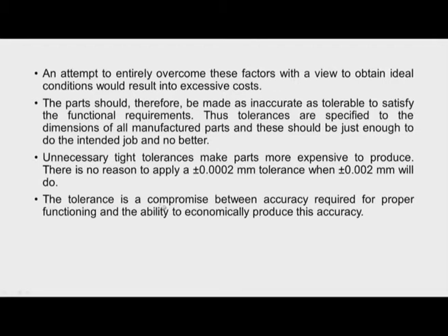And then tolerance, we should understand that the tolerance is a compromise between accuracy required for proper functioning and ability to economically produce this work to produce the accuracy. We should always understand that while specifying the tolerance the need should be satisfied, as well as we should consider the manufacturing aspect, so that the product can be produced with economy.